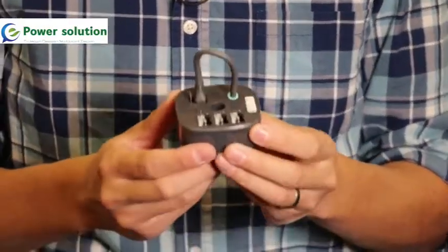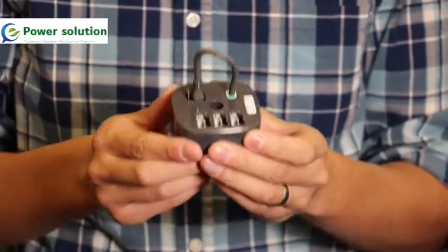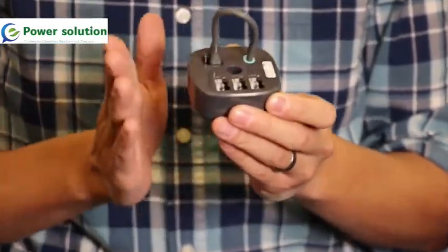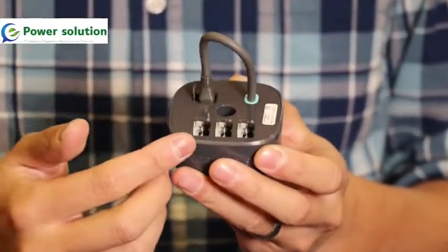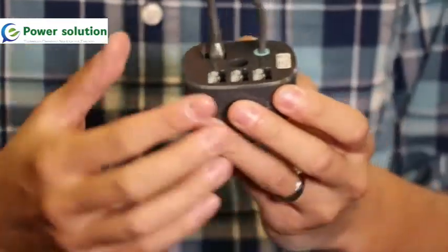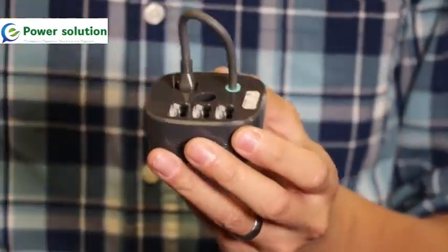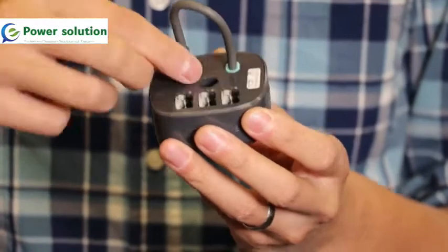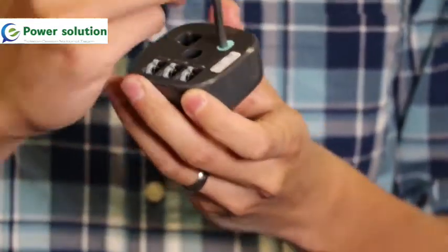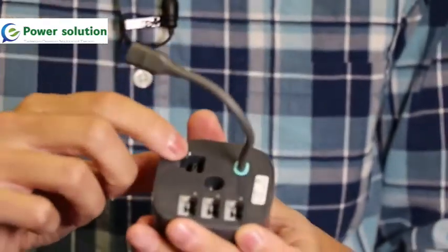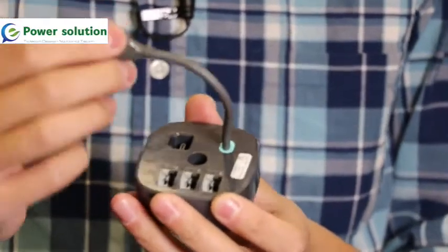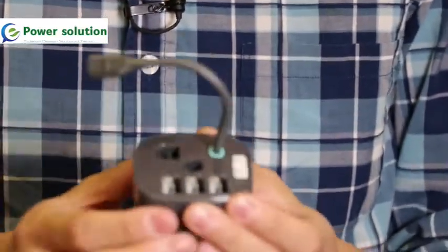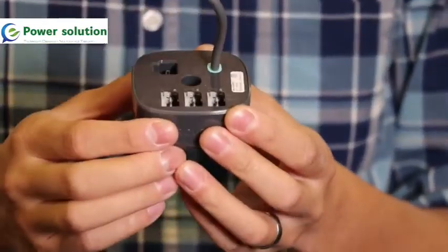The next component of our system is the generic interface module. You would utilize this module for connecting to loads beyond what our Smart CT can handle, generally loads about 90 amps and above. This module utilizes the same data interconnect and the same data socket, so it can daisy chain along with the Smart CTs or other generic interface modules in your system.